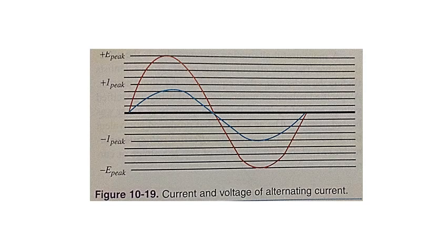Referring again to figure 10-19, the maximum rise of the waveform shows the amplitude of the wave, including the peak, highest point, voltage, and current. We learned that induced current in a rotating wire in a magnetic field flowed first in one direction and then in the other direction. This was defined as alternating current. The points to remember are the frequency of this cycle of events increases as rotational speed increases. The amplitude of the induced voltage depends on the strength of the magnetic field.